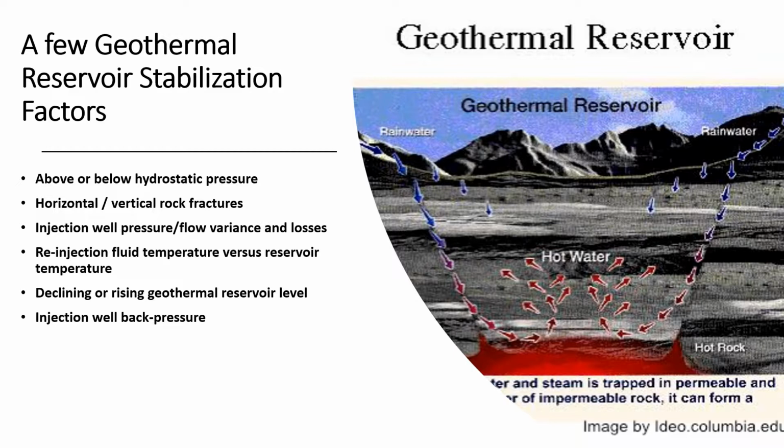For example, higher in situ reservoir pressures require higher injection well pressures, in turn impacting pumping costs. On the other hand, vertical rock fractures, when present, lend themselves to gravitationally injecting the reservoir, assumedly at a lower cost. Are rock fractures primarily horizontal, or are vertical fractures present? How extensive are these fractures? To what extent does the fractured production zone extend beyond the return well envelope?